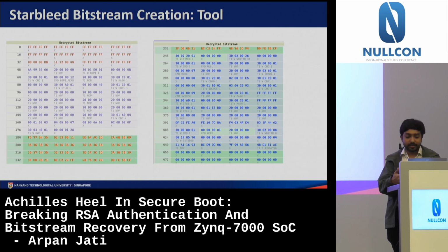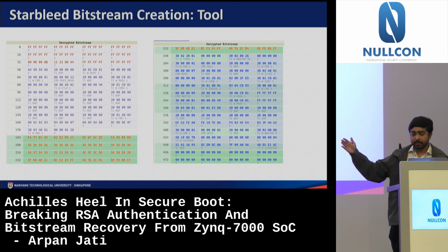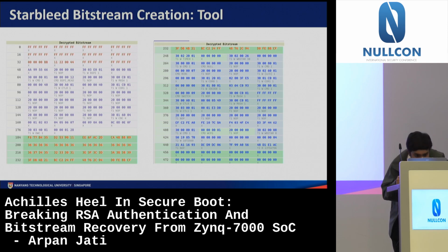So is it clear? It's a bit complicated to explain, but what you are seeing is a decrypted bitstream. In actuality, it will be an encrypted one, but the tool is showing you what will happen if it is decrypted, how the FPGA sees it. This part is actually decrypted, but the encrypted part you can copy from all of the image. The image is very large. You can copy 4 words at a time, and then replace this 408 line.